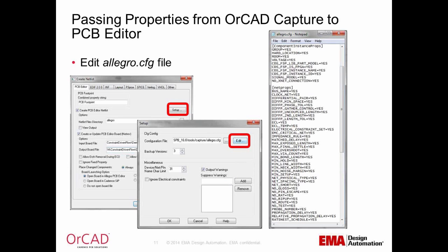like each component group to be placed. These rooms may have constraints associated with them. As an example, rooms may be defined on top side only, bottom side only, or both sides of your board. You may assign a room a hard property, which will require all component members to be placed completely within the room and no non-members will be allowed. Or you may also assign a room a soft property, which is treated more as a suggestion rather than an